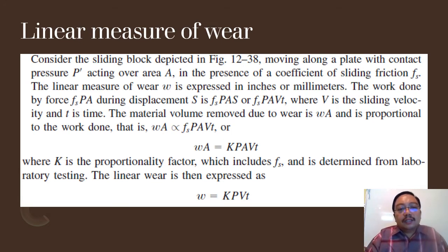Consider a sliding block in figure 12-38 moving along a plate with contact pressure P acting over area A in the presence of coefficient of sliding friction fs. The linear wear measure of wear W is expressed in inches or millimeters.